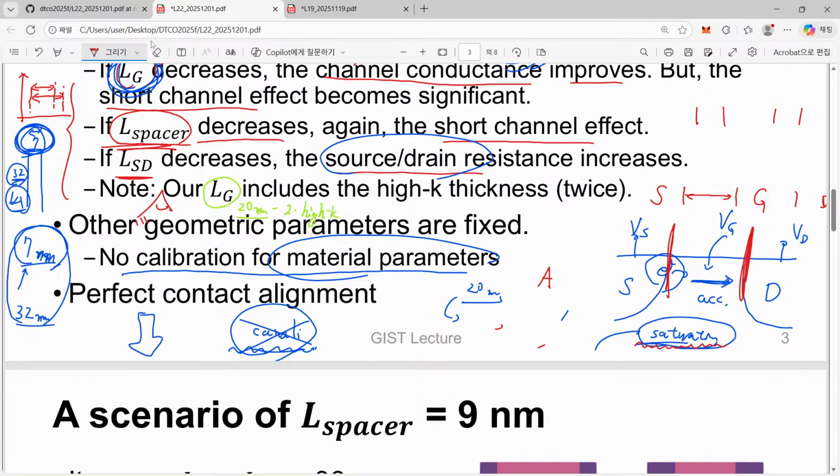So if the electron speed goes too high, then there are higher chances of a scattering event, and its velocity goes down to this saturation level, whenever the driving force, the highly biased drain, tries to accelerate our electrons even higher. However, if it arrives at the high velocity regime, then it has higher chances to be scattered. So are you with me?